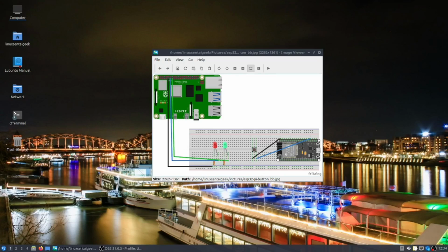One side of the button connects to ground and the other to pin 15. You can use any other pin assignment you want, and you can pretty much use any kind of ESP32 you want. So that's really it for the setup. I'm sorry I didn't add it, so back to the video.